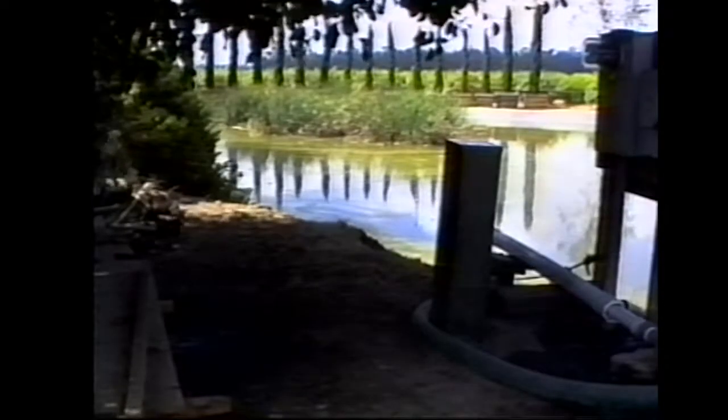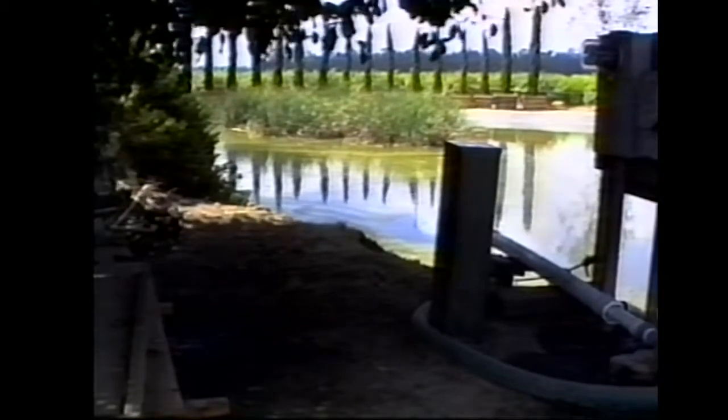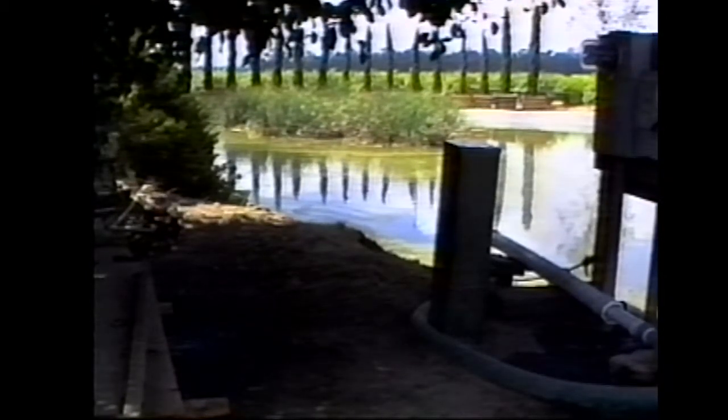Water sources for drip and micro-irrigation systems include rivers, reservoirs, municipal water, canals, and groundwater. Each of these sources may be contaminated to varying degrees by organic and inorganic materials. All modern irrigation systems need to be protected from these contaminants. Filtration for drip and micro-irrigation is a challenge because water quality and the nature of contaminants can change with time.